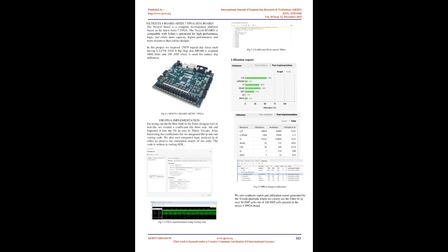Below is the graph of order of filter versus settling time. The above graph is obtained by using the filter function from Matlab. One can obtain a similar graph by keeping the pass value constant and varying the stop. In our case we varied the stop from 10 to 100 Hz. By varying these values we observed that as the difference between stop and pass increased, the order of the filter started decreasing, and we obtain settling time using the step impulse function.